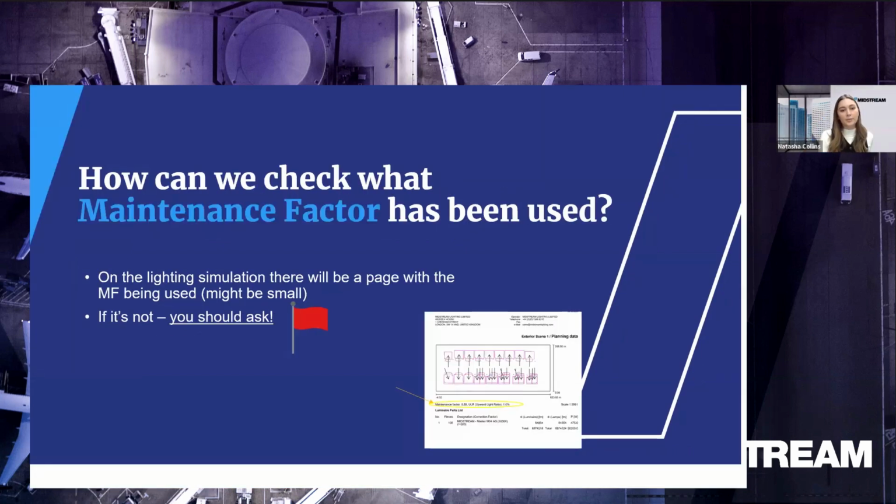Thanks, Paolo. So finally, where can we actually find the maintenance factor? How can we check that it's been used? Well, depending on the software used, for example in Dialux, it's found on a page called Planning Data, where you have a kind of summary of luminaires used, lumen outputs, power. It's always indicated right there.